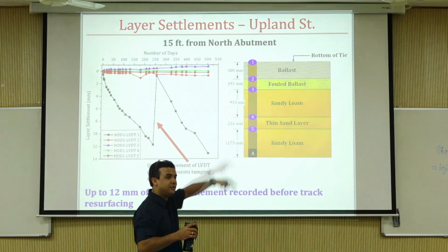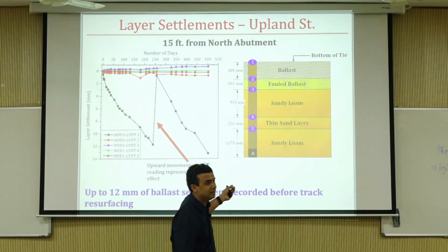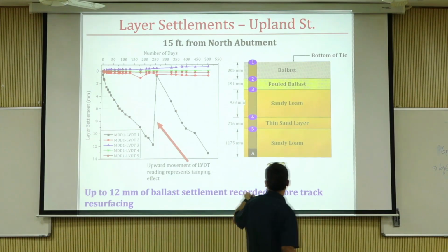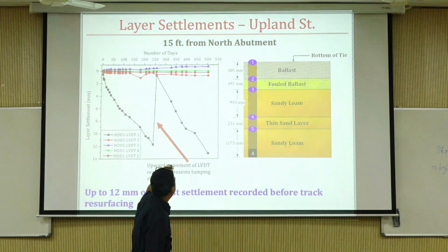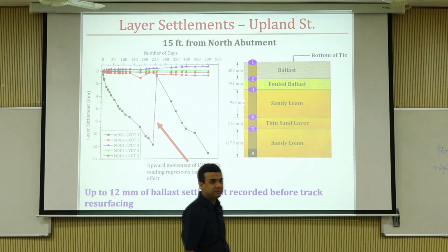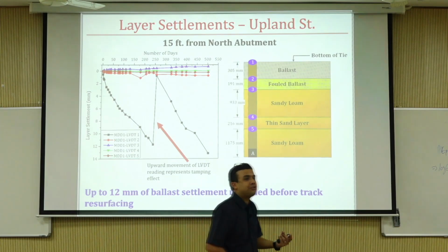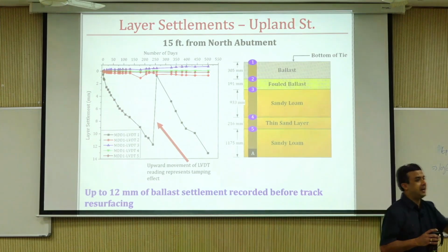But this project is what propelled us, because nobody had done this in the world, and we identified that the permanent deformation you see in railroads is mostly coming from ballast. Everything else, look where they are standing, almost negligible. So it's your rocks rearranging that cause all the track defects.